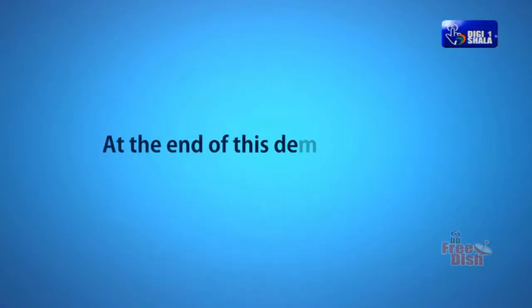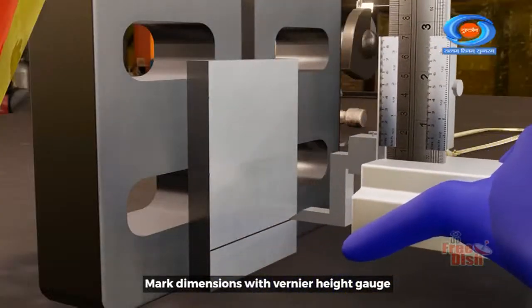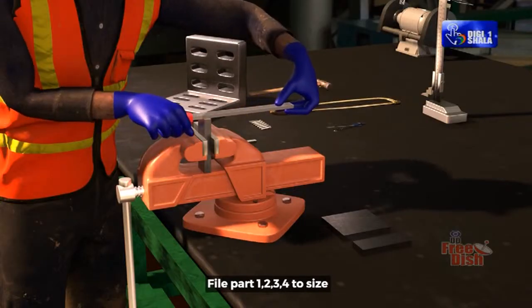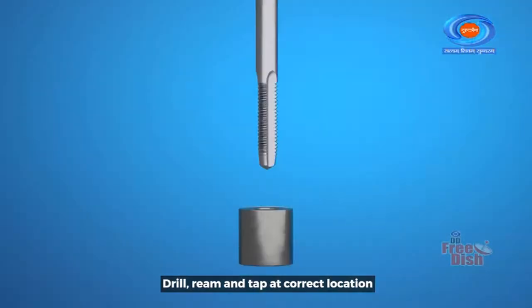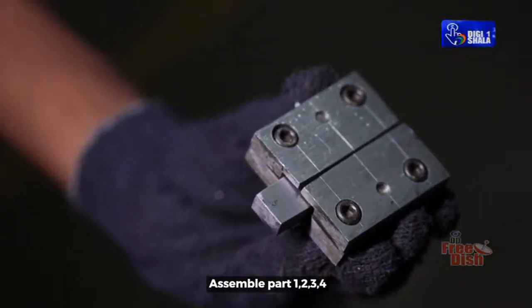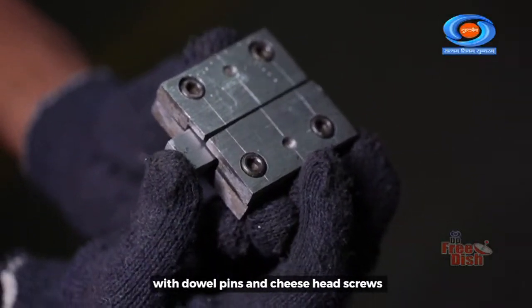At the end of this demonstration, you will be able to mark dimensions with vernier height gauge, file part 1, 2, 3, 4 to size, drill, ream and tap at correct location, counterbore to the required depth, assemble part 1, 2, 3, 4 with dowel pins and cheese head screws.